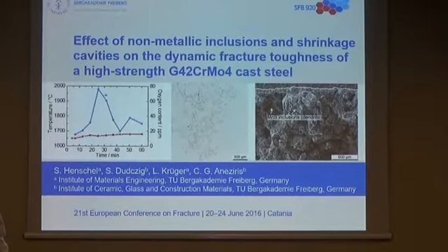We have the temperature and the oxygen content measured over time. First we oxidize the steel melt with addition of iron oxide, and then we deoxidize it with pure aluminum. And what follows is, after cooling, a cylindrical steel specimen with the dimensions given, and from this cylinder samples were cut for metallographic investigations, tensile tests and fracture toughness tests. And due to the cylindrical shape we also use cylindrical coordinates, which are given here.